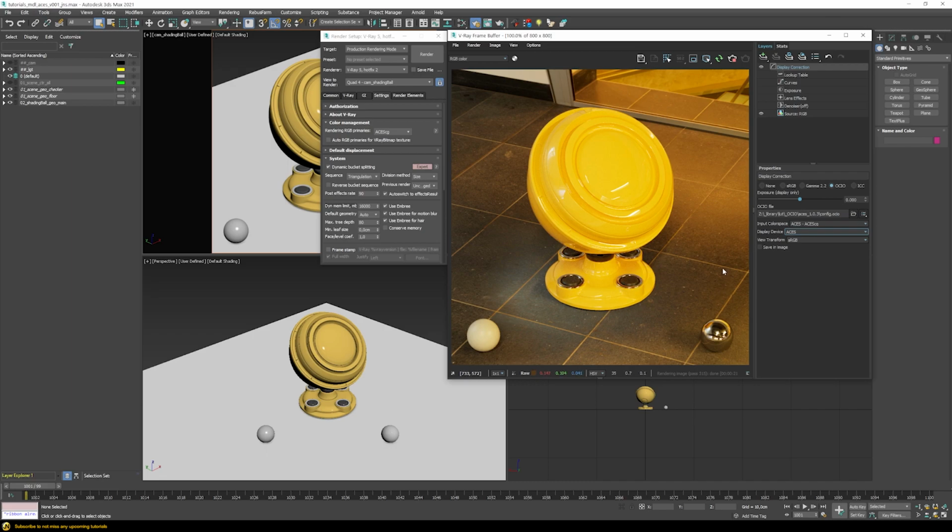And the advantage is that this kind of result you would now be able to transfer exactly to any other software package. So you can load the same configuration in Nuke and you will get a very consistent, exactly the same result as here in VRay. But the disadvantage is that you now don't have these sub controls here anymore about exactly what's happening internally. It's basically all handled now from this OCIO file right here. But if you work with ACEScg, this is a very good option that you should basically consider using.